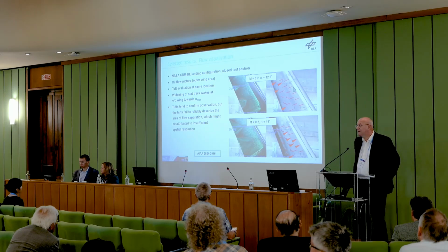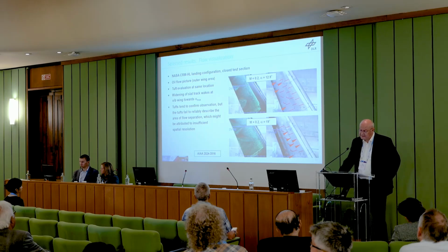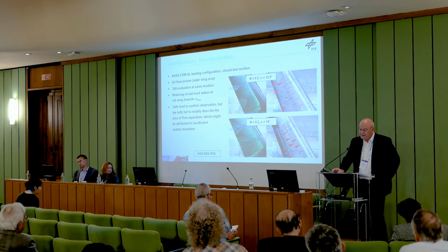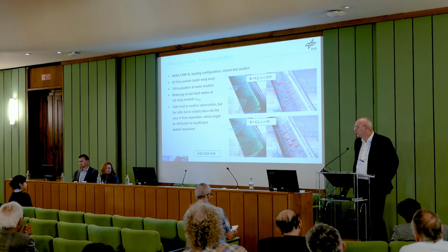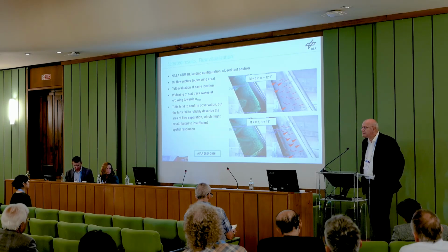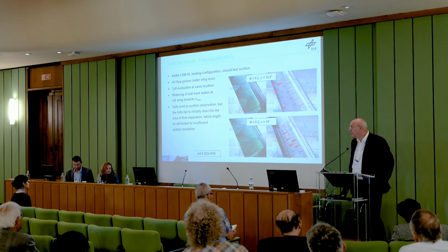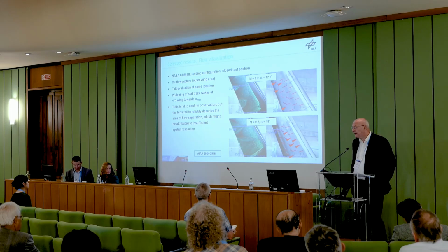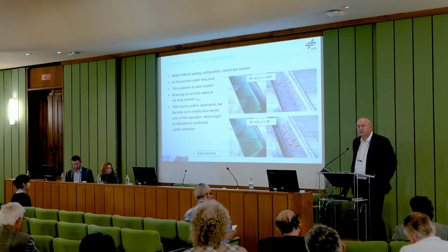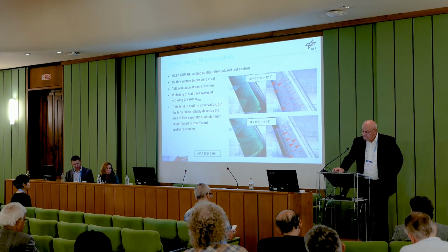And we did at the same time some tuft visualization. And the shape of the single tufts here is an indication for their state. So we have attached flow. The triangles correspond to excited tufts, and the shapes down here correspond to flow separation. If you compare the two, well, the tufts give an indication where separation starts, but of course they are by far not as valuable as the oil flow pictures are. Maybe a reason of resolution, so you want to bring more tufts on the wing, but at some point, if you have a high tuft attachment here, then you start to have an impact on the flow, so that's maybe not the way to go.